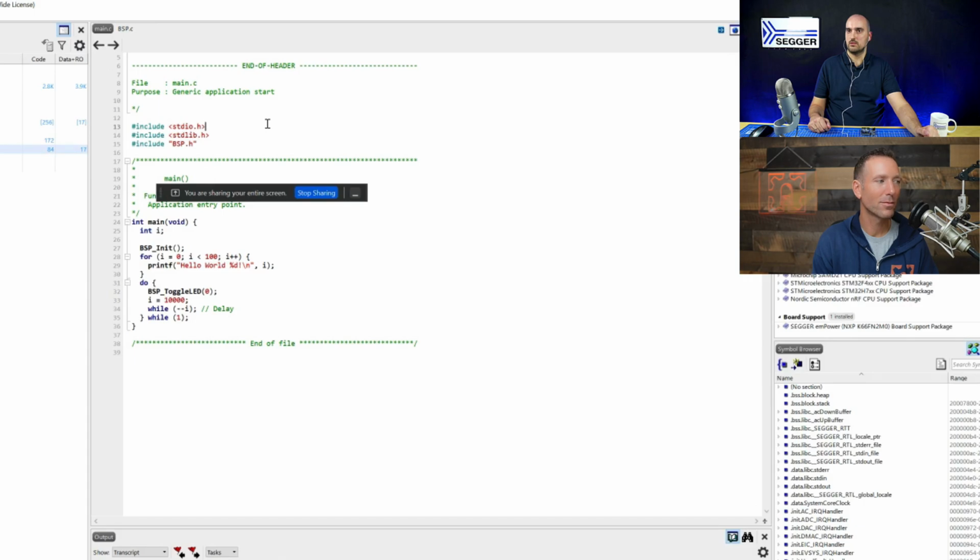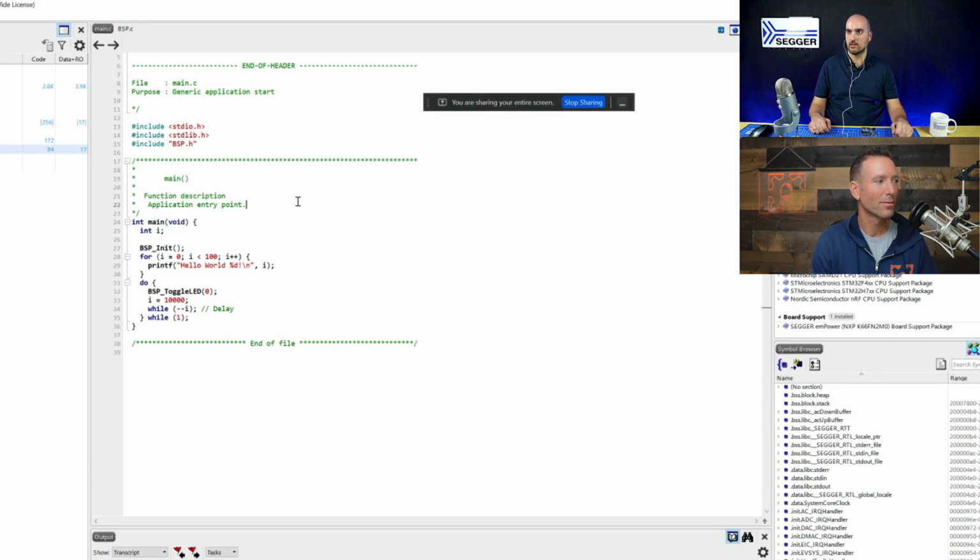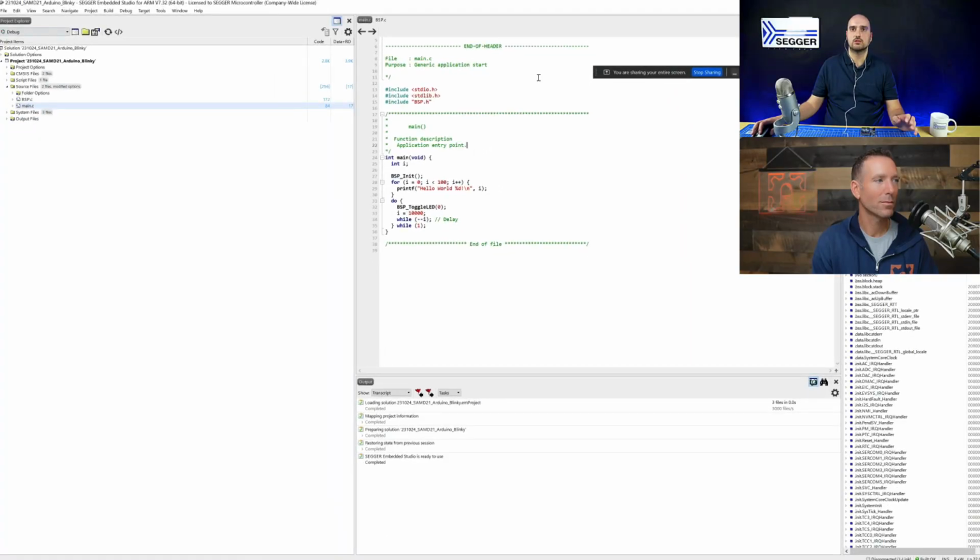Because as we saw earlier in your demonstration, a lot of stuff happens before main. And this takes away a little bit of memory space. It might also do some interrupts without your knowledge in the background, which maybe you don't want when you're doing something more time critical. And if you go bare metal, you literally have full control from the reset handler. So what happens directly after reset, the first instruction that is executed, you have essentially prepared or written it.